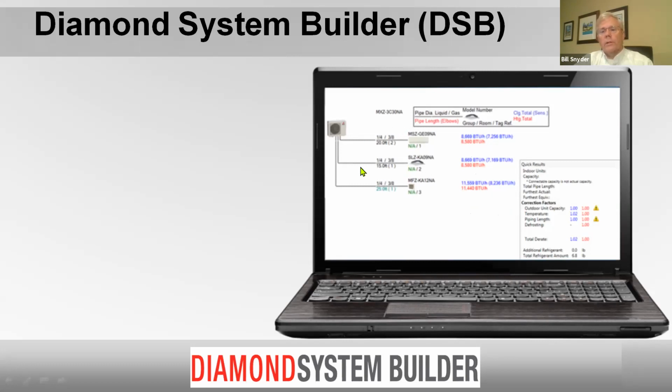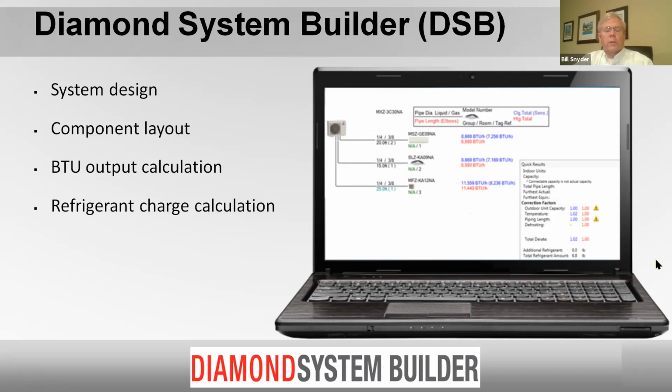After you do all this, right down in here, it says additional refrigerant required. This is a 1-to-1 unit, so there's no additional refrigerant required. But if this was a branch box unit, it would require additional refrigerant. So it's kind of neat. It does a system design, component layout, a BTU calculation, and a refrigerant charge calculation. You can save this, print this out, send it to the job site as a PDF document.